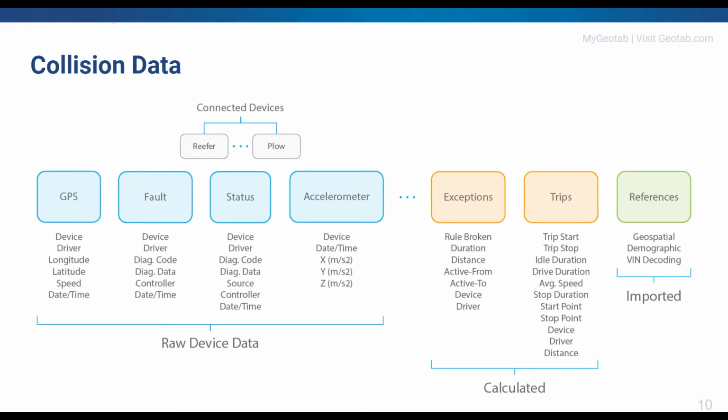So this VIN decoding is also one important step here. So only focusing on the collision data itself. For the GPS information, importantly is that we have a buffer. So we are buffering a certain amount of data. So actually 100 minutes of second by second GPS data logs are stored on the device itself. So those are 6,000 logs.